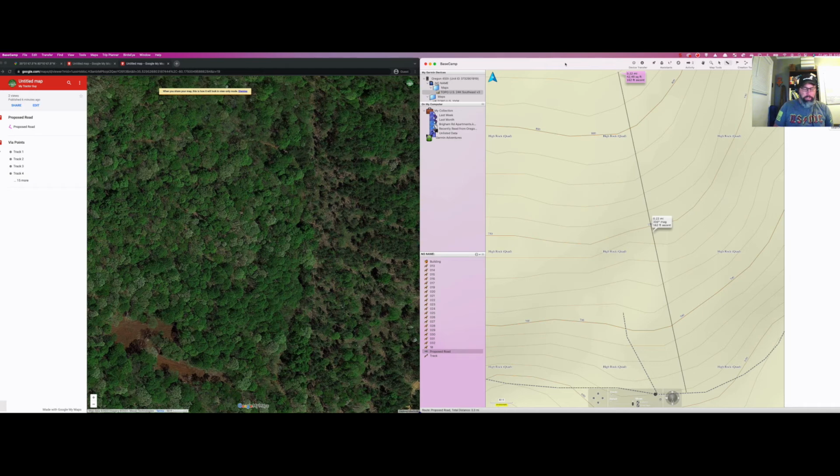So there again, you say 5,280 feet in a mile times 0.22. That's 1,162. So 162 divided by 1,162 gives us 13.9, almost a 14% elevation gain.